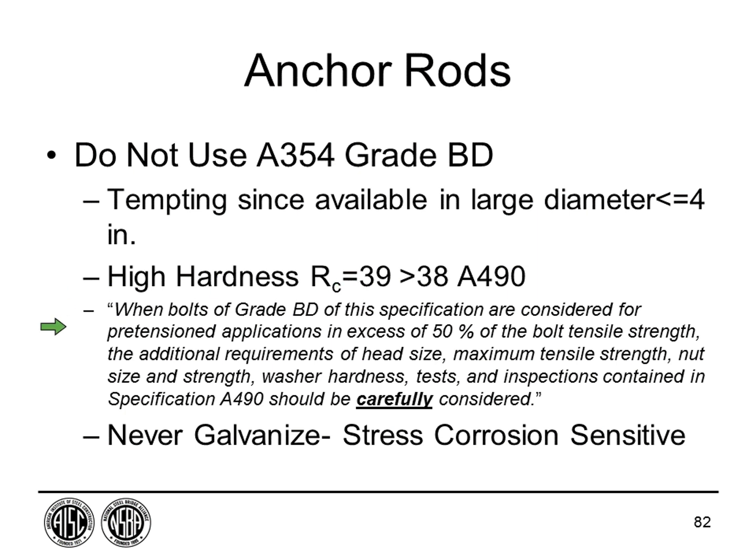It also has this note in the specification. It says that if you're going to tighten them up to above 50%, you might want to look at the A490 specification. And some of my advice is to never galvanize them. They're very stress corrosion sensitive. Now there's work going on to change the specification to reduce this hardness and hopefully improve it. But right now, as it stands, you should be aware.